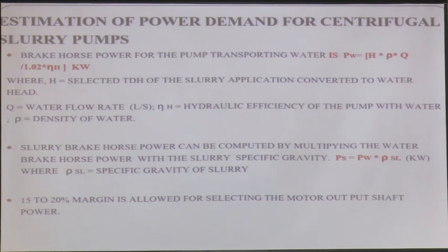What is hydraulic efficiency? You have seen the efficiency curves, right. So, by comparing, to start with, you can say okay, I will consider 72% efficiency. Eventually it may lead to 78% also, but to start with do not take the high figure, take a little bit lower figure, so that your numbers are bigger and you can enjoy the credit of saying oh, I have reduced the numbers when the actual project is getting commissioned, right.